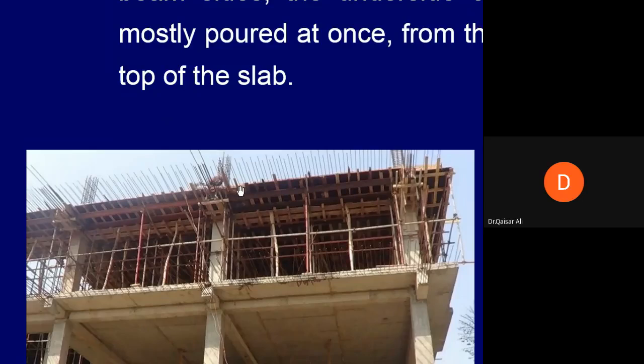Like in a steel structure, you would have seen a T steel section, where the top portion is called the flange, and the remaining bottom portion of the beam is called the web portion of the T section. So similarly, this part which is below the slab will be called the web technically, and practically the people in the field, they call this a hanging part of the beam, and part of the slab is called a slab.